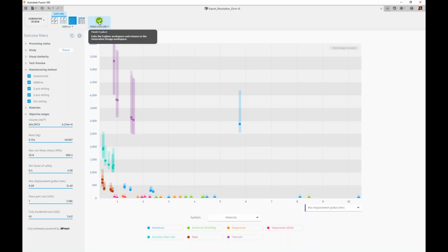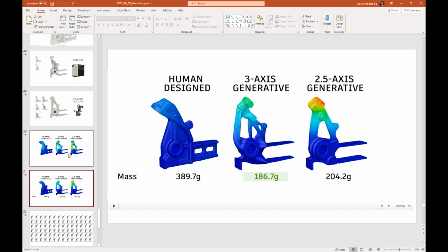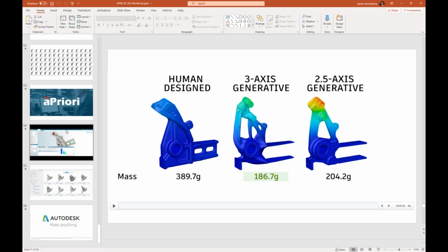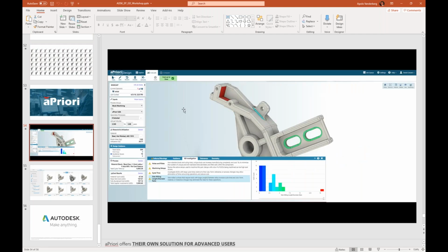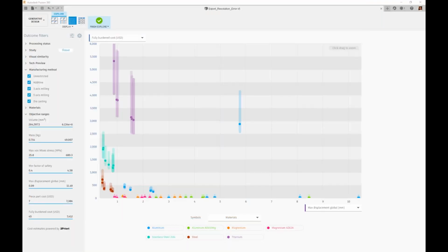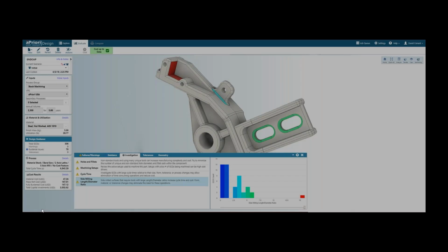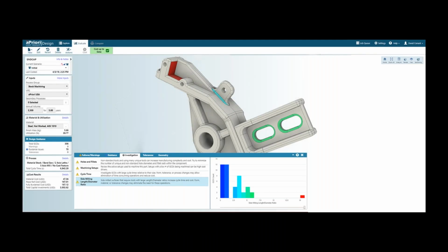The larger the safety factor that is applied, the more beefy or rigid it's going to want to make the part to keep the stresses low. So you could go a little less conservative on the safety factor as well. Mm-hmm. Yeah, that's another valid point.